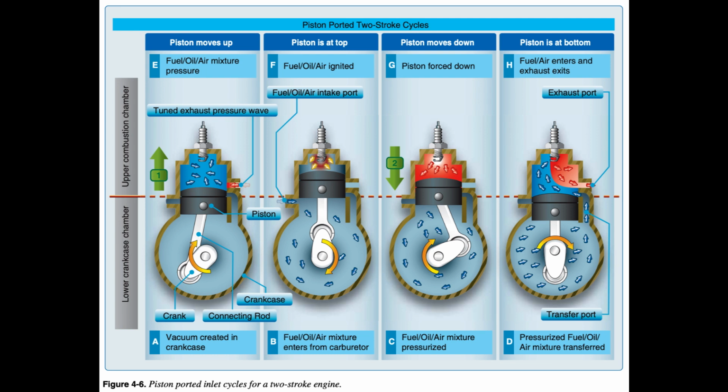When hot spent gases are vented out of the exhaust port, they are moving fast enough to set up a high pressure wave. The momentum of that wave down the exhaust pipe diffuser lowers the pressure behind it. That low pressure is used to help suck out all of the residual, hot, burnt gas from the power stroke and at the same time help pull a fresh fuel/air charge into the cylinder. This is called scavenging and is an important function of a tuned two-stroke exhaust system. Figure 4-6h.